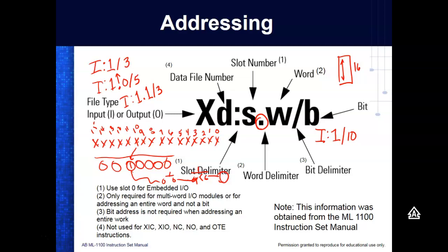One thing you got to remember is that when you buy the PLC, you got to buy enough inputs to manage your system, right? And this is what's nice about a modular PLC: you can add more modules. A fixed PLC, you get exactly what you buy. So if that PLC's got 10 inputs, that's all you got is 10.